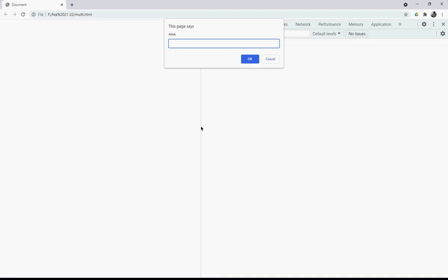Okay. So now it is asking me area of first element. So 100. Modulus of roughly 2e5. Start node number is 0. End node number is 1.